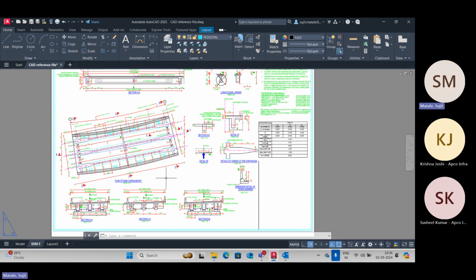Okay. Basically, you have a relationship between stiffness, displacements and forces. There is an equation you solve; the displacements multiplied by the stiffness give you the forces. I don't want to get into the depths of it because we really don't need it in our practice. But that is the core of every single finite element program.